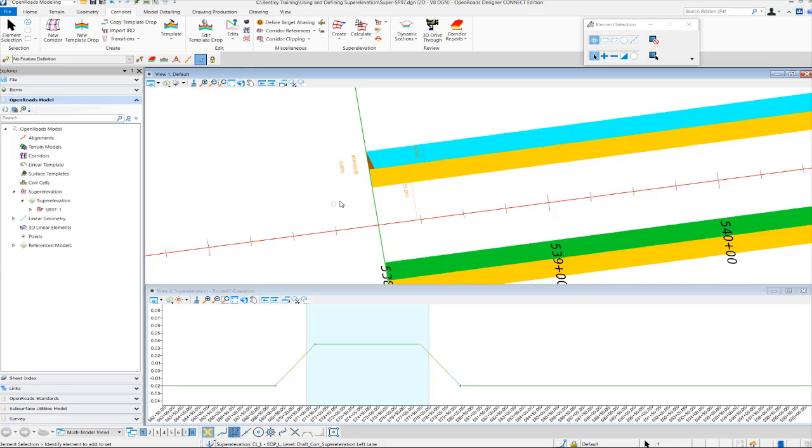Sometimes it's necessary to match an existing cross slope at the beginning or the ending of your project. So what I want to do in this example is match our existing cross slope of minus 1.6% for these particular lanes here. I want to show you how we can add a transition to our lane. The first thing I'm going to do is select my westbound lane here.